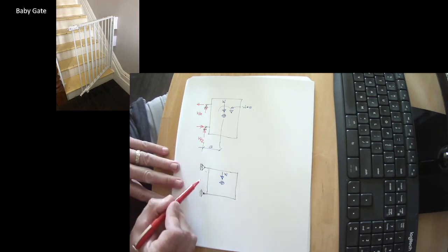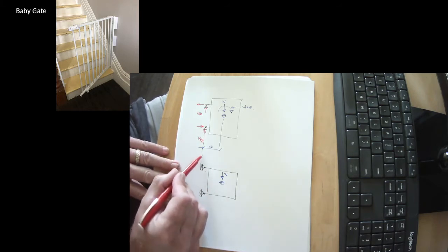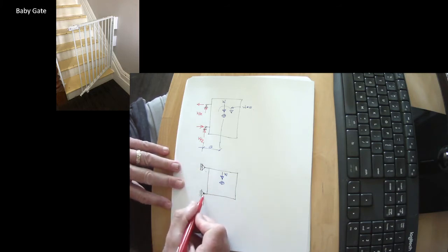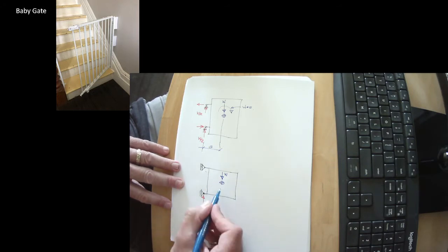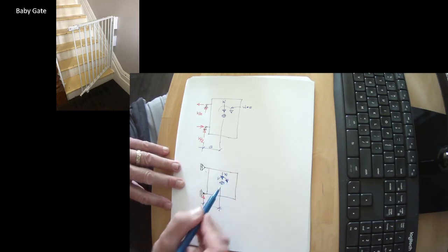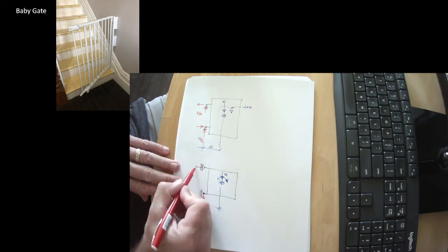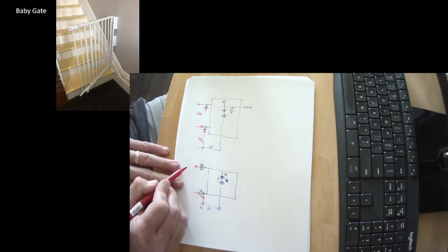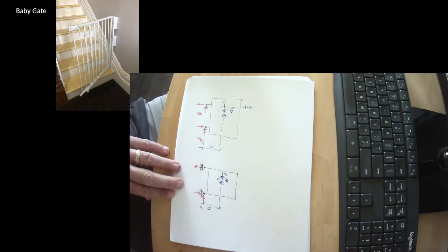So the upper hinge is modeled as a roller. It carries no vertical load. The lower hinge carries all the vertical load, weight. So we have weight, we have weight. You can see that once again we have eccentricity, which results in a moment, a tendency to rotate. What's that resisted by? Well, it's resisted by a horizontal couple. It's pushing into the wall on the bottom, pulling away from the wall on the top.